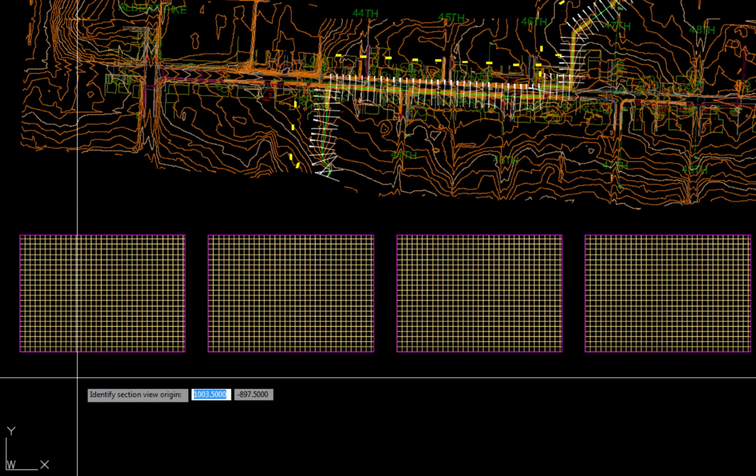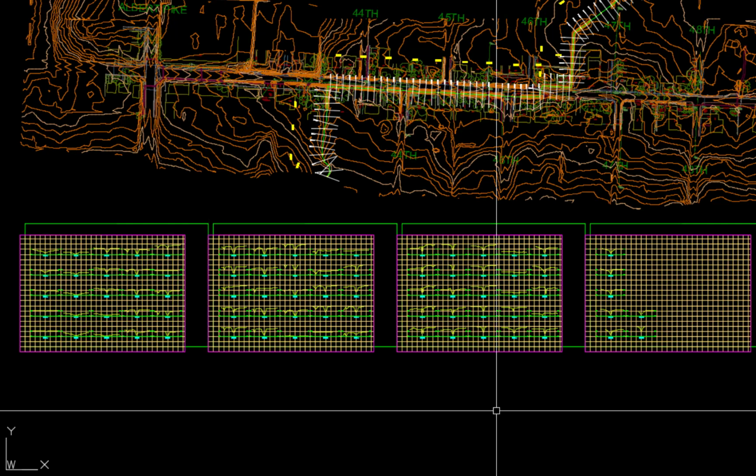If the grid sheet is displayed, you can select the intersection of the first vertical grid line to the right of the left border with the first horizontal grid line above the bottom border. If the grid lines have been inserted, erase the Civil 3D green border. Enter to start the erase command. Select the green border and enter. Cross sections are recreated. Section sheets that are created by the draft method can be moved without worrying about them being deleted when the drawing is saved and then reopened.